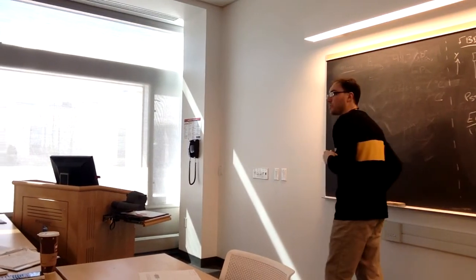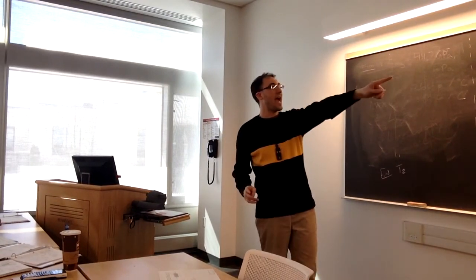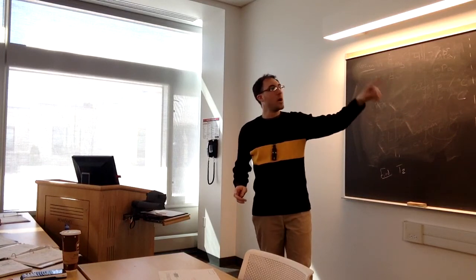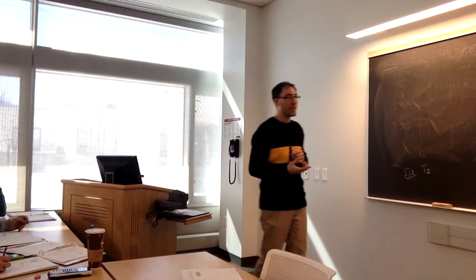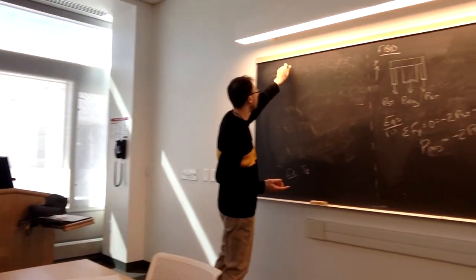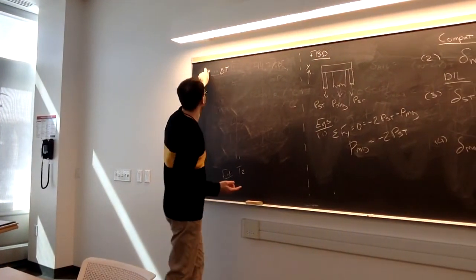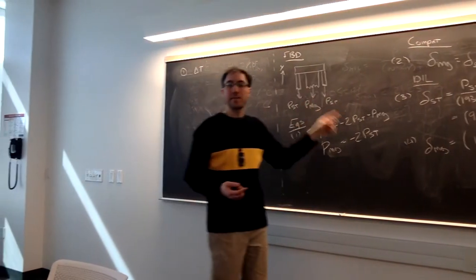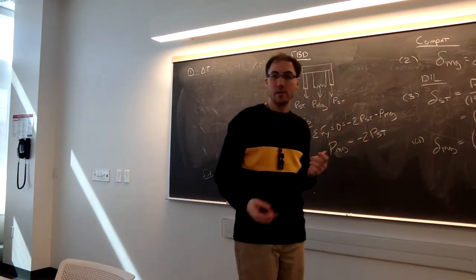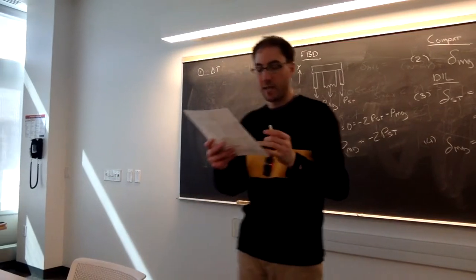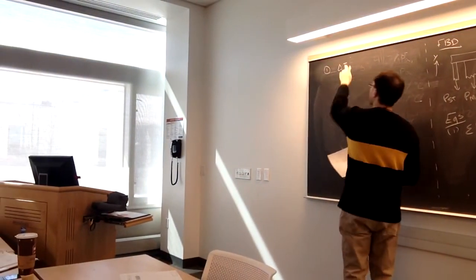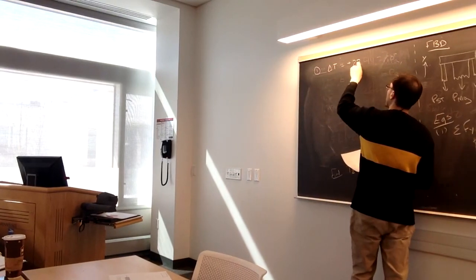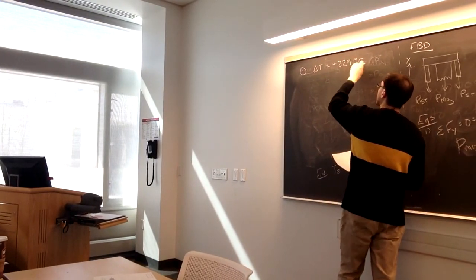I won't go through the algebra steps, but if we look at equation 5a, 1, 2, 3, and 4, we now have 5 equations for 5 unknowns. So we can solve for delta T when we're using these 5 equations. So for the steel to have 12 megapascals of stress, that delta T is going to have to be positive 229 degrees Celsius.